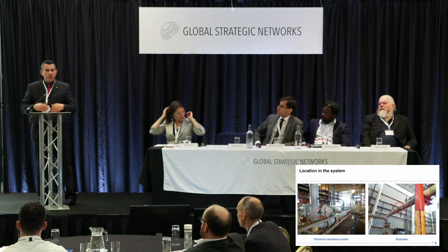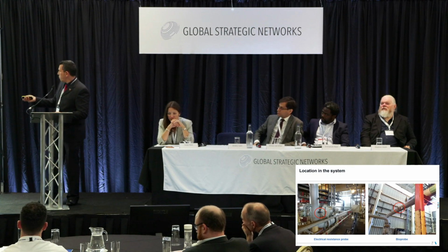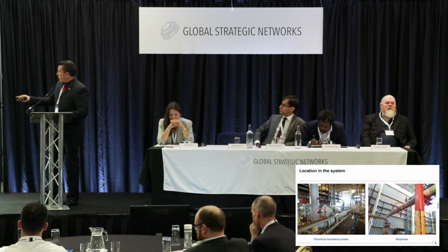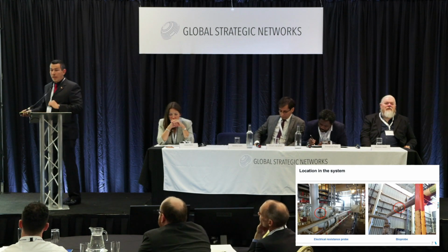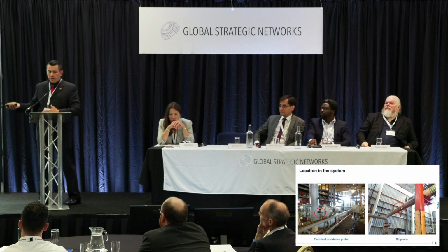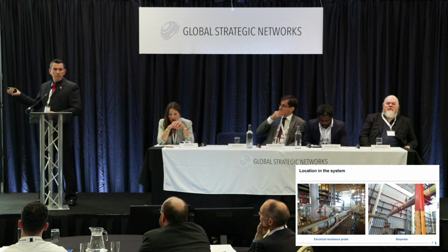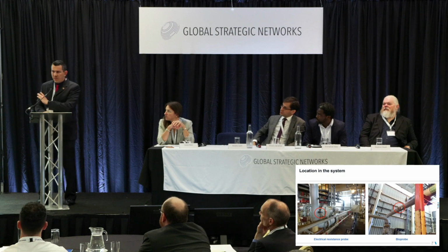I also want to share part of my experience. Sometimes we have corrosion probes installed in our assets. Here we can see one. It's easy to recognize because they have this typical small chain and a lid to cover it up. And then we can know that it's there. But sometimes we also have this type of access fitting close to another one. When there is not experienced personnel in the field trying to find it, they might have some challenges. That's why documentation is important. That's the message that I wanted to give with this slide.